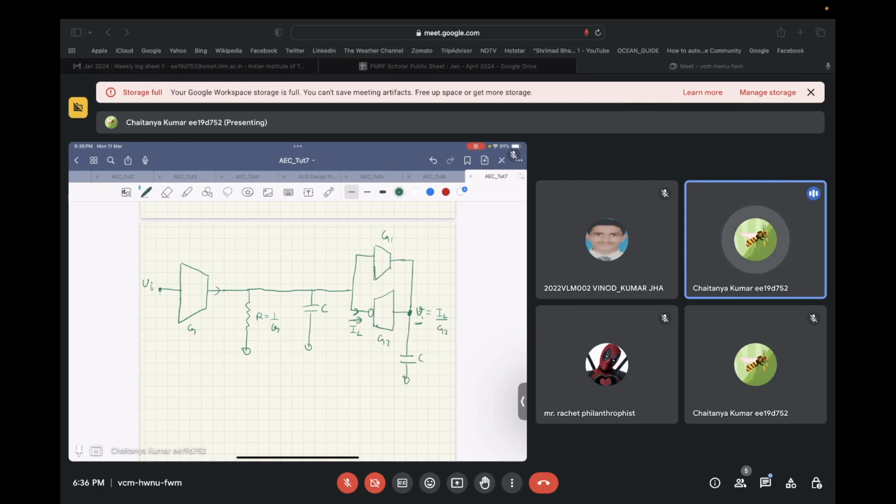So initially we saw that the inductor current is a low pass filter. Now this particular voltage is proportional to the inductor current with just a scaling factor of G2. So that means this voltage will also have a low pass transfer function. Is this clear?